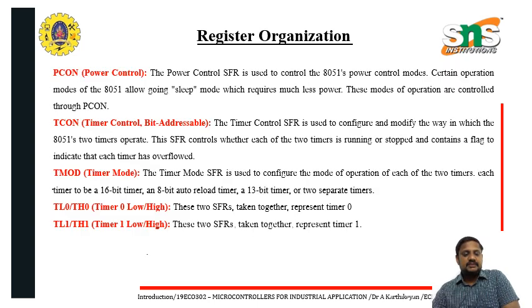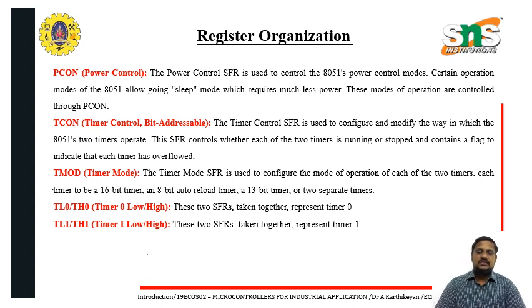The next one is PCON, the power control register, an SFR used to control the power modes of the 8051. Certain operation modes of the 8051 allow it to go into sleep mode, which requires much less power consumption. It is turned on only when needed, and the remaining time it stays in sleep mode, so power consumption is reduced. The modes of operation are controlled through PCON.